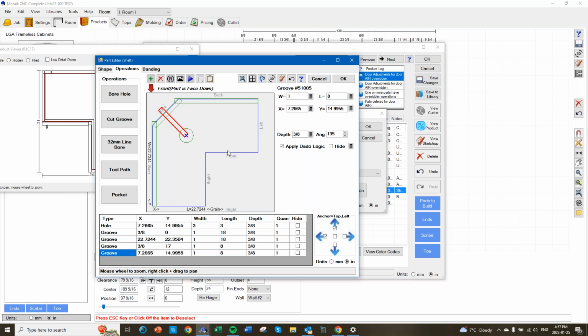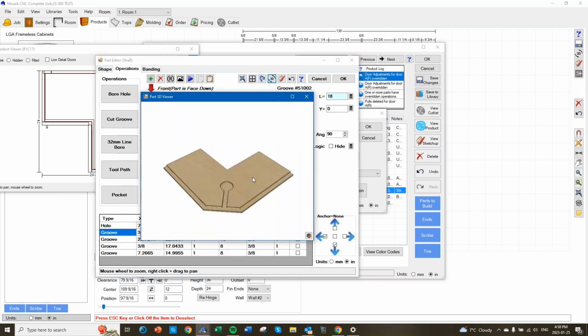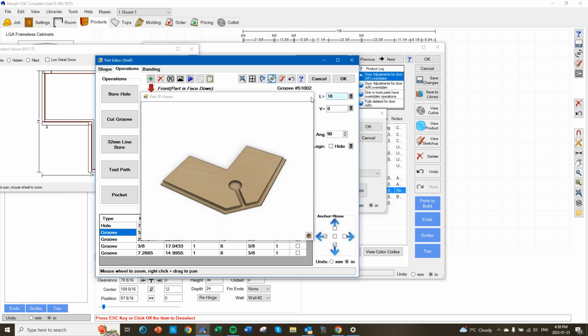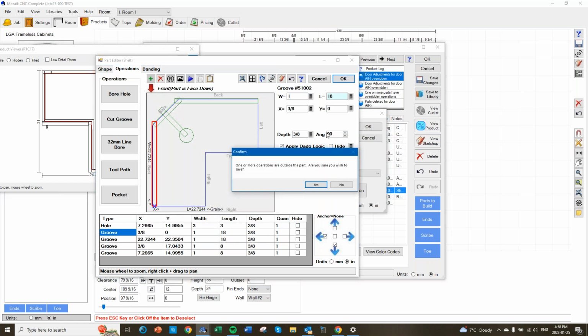So we're going to anchor all. This one we anchor to the back corner. This one we're going to anchor to the top back corner. It's going to stay there. This one's got a formula on the X and Y, so it doesn't matter about anchor point. This one too. On this one, we're going to anchor at the bottom left because we don't need a formula on that. So now this part is going to look like this. Yeah, correct. Okay, let's click OK.